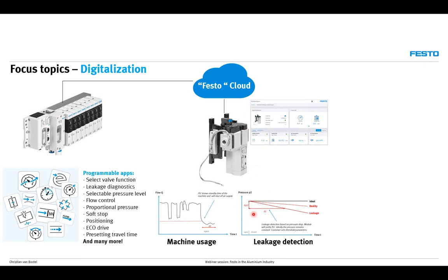Also, for example, because this product has an on-off valve integrated, we can shut off the device, which will be triggered by the PLC after a certain time when the machine is not being used. In the meantime, the air supply to this machine is stopped, and this way we can save energy and also avoid risky situations because the system is unnecessarily pressurized.